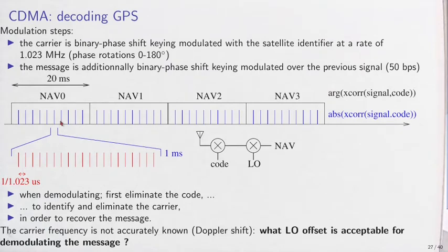that was transmitted. Each navigation bit is transmitted for 20 milliseconds, 50 bits per second, so that we have 20 repeating same phase values of a correlation output. And by looking every 20 milliseconds at the phase value, we can recover the navigation message.